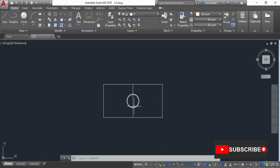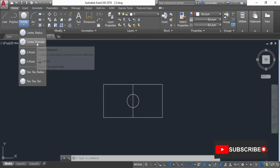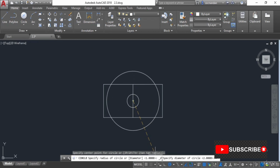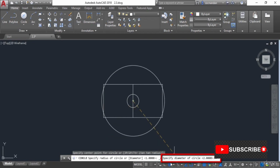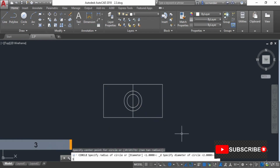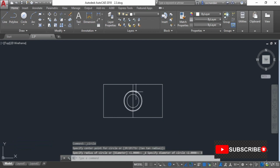Now let's look at the other method of making the circle. So go to the circle flyout and select the center diameter, and in this case we need to specify the center first. And obviously when you look at the command line, you'll notice that the radius option has been overridden, and we have this option now which says that we need to specify the diameter of the circle. So let's type 3 as the diameter and press enter. And now here we have it, the circle with a diameter of 3 units or a radius of 1.5 units.